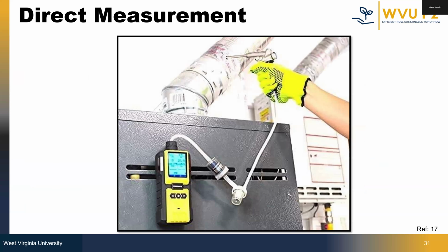So the measurements from a combustion analyzer, along with software like Measure, can be used to determine the air to fuel ratio and calculate potential energy and cost savings for making adjustments to the boiler. So after measuring the ambient temperature, combustion air temperature, stack temperature, excess air, and emissions using the combustion analyzer, Measure's flue gas loss tool can be used to determine the amount of excess air.